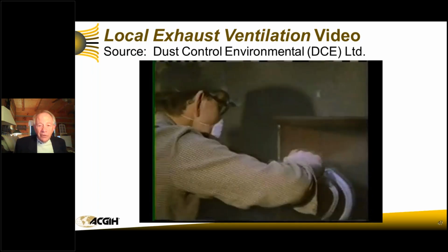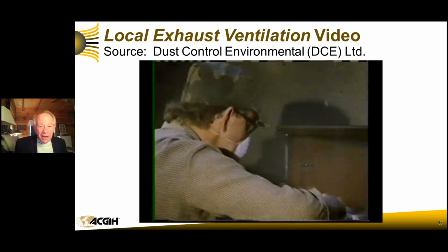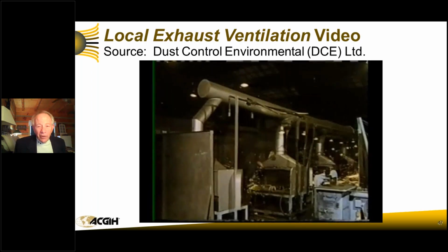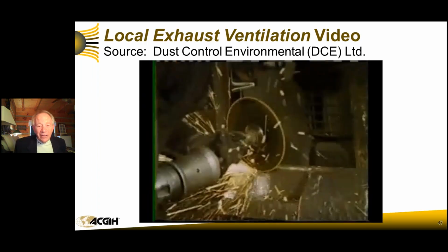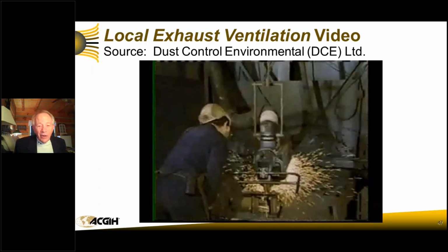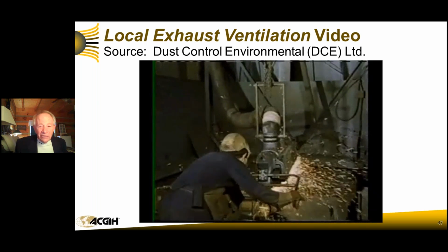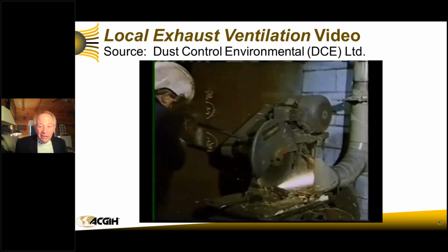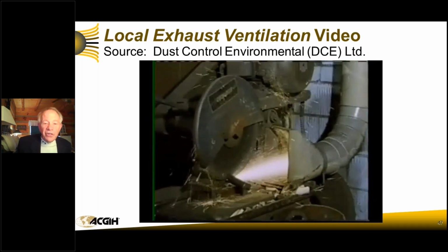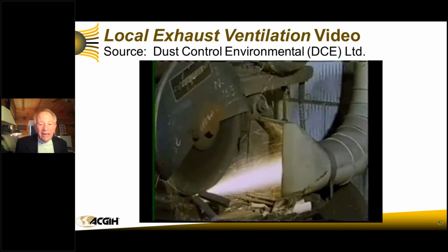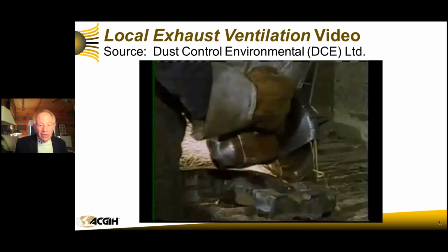There's a paint spray booth. Notice the projection is causing a backflow. And of course, he's not wearing a respirator with activated charcoal either. So notice on this one, here they are, they're grinding and they're throwing the particulate contaminants outside the hood. Here is one that projected directly into the hood. Now we're getting virtually 100% capture.